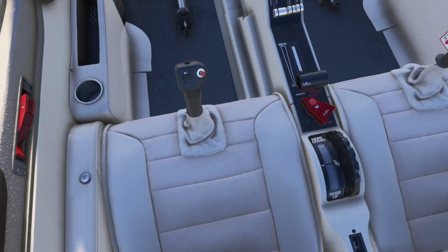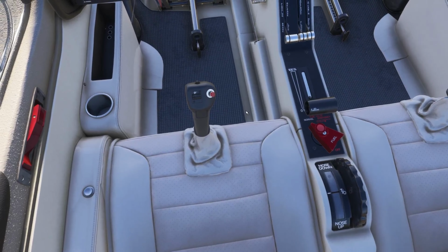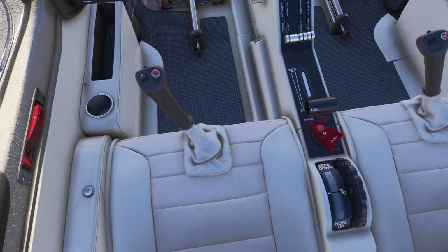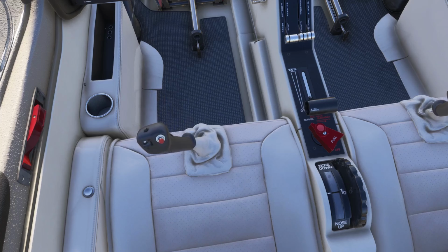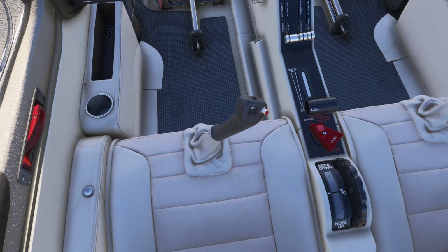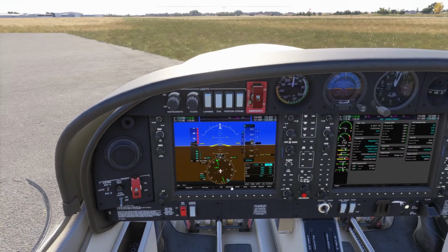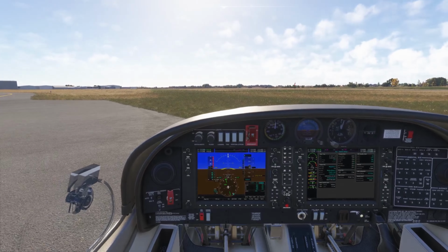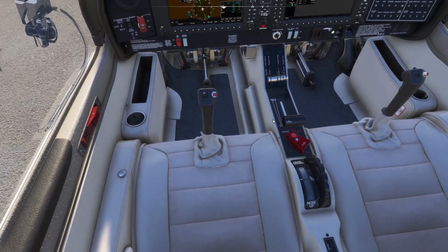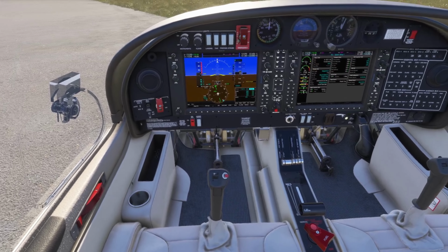Flight controls, full free movement. So how we do the flight controls on a light fixed wing aircraft is we go full forward, keeping it full forward we go fully to the left. Then we go fully to the back left, fully to the back right, fully down, and centered. So we're checking the four corners of the flight controls, and that's fully free now. Then we're going to check power lever is idle, which it is, and then we're going to do ECU test.